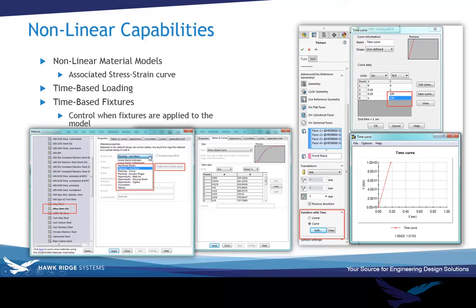And you also see that I have more material model types. Aside from linear static, aside from a linear material, you can define this plasticity von Mises, which defines a stress-strain curve. Or again, if you're dealing with rubbers and hyperelastic materials, we have a hyperelastic material model. And when you review the stress-strain curve, I didn't input that manually.